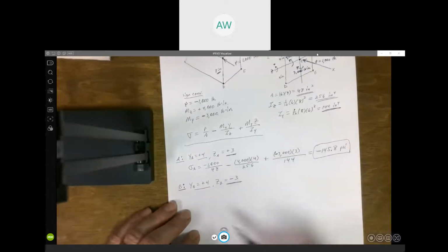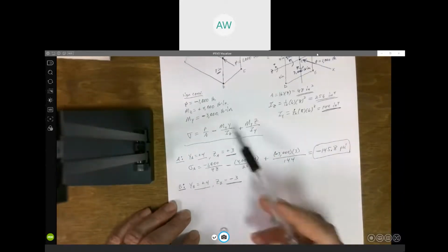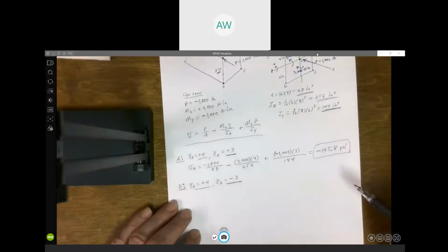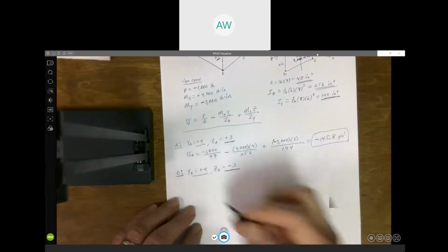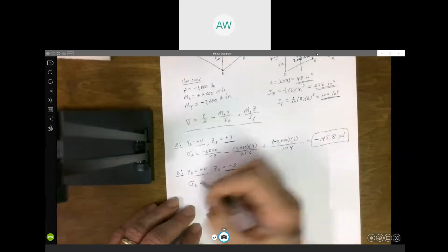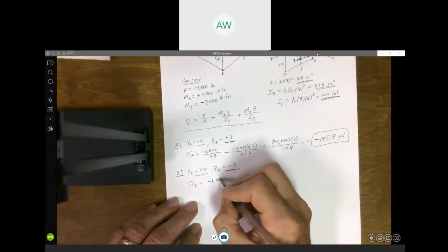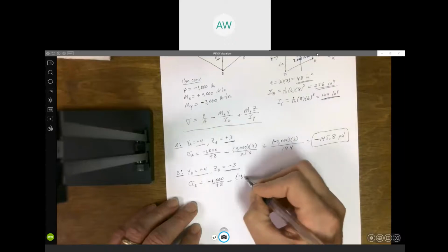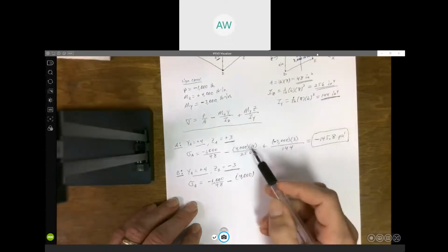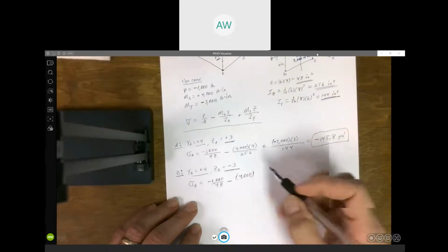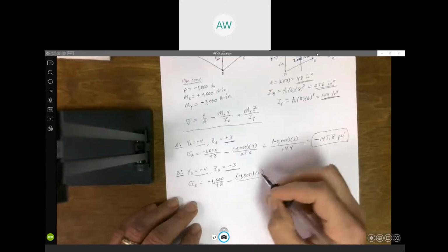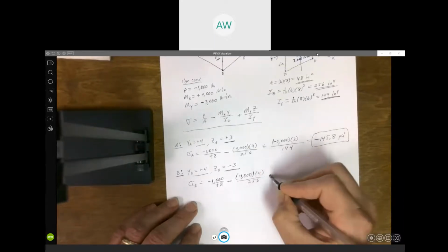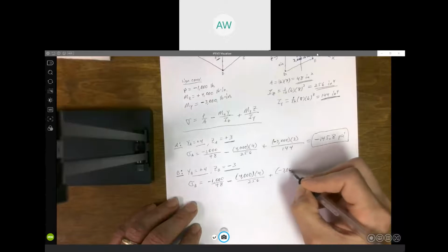And we plug those values for y and z into the formula, and we get the stress at B. So the stress at B is minus 1,000 over 48, that doesn't change, minus 4,000, y is still positive 4, over 256, minus 3,000.